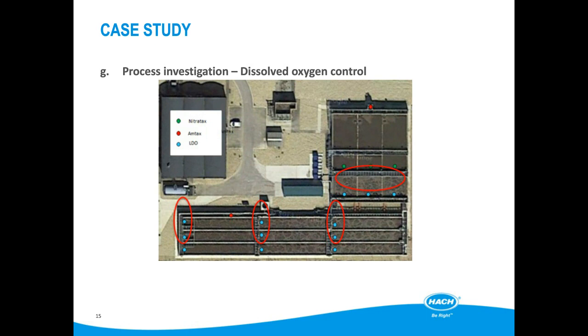We adjusted the set point factor to shift the ammonia treatment priority up the lane, allowing us to require less DO in Zone 4. A further improvement to the model was to account for hydraulic retention along the lanes. This ensured higher DO set points were only requested at times the higher ammonia load was in that zone.